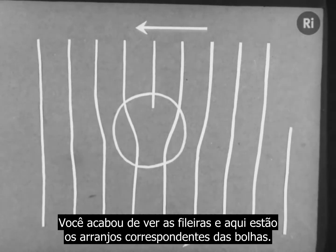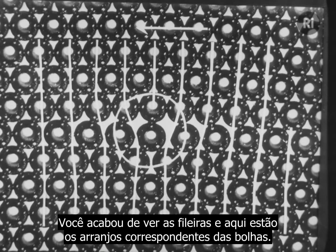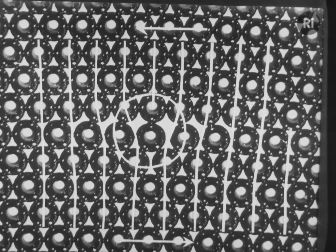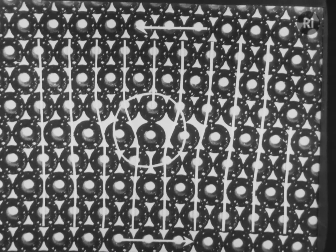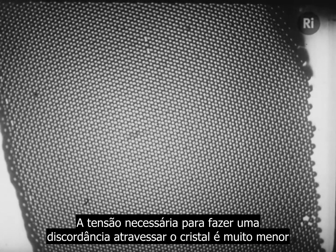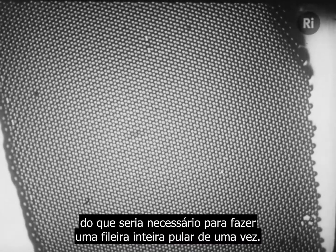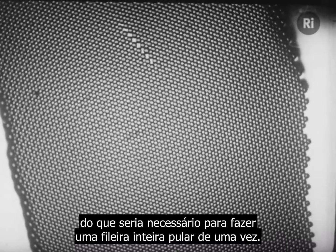You've just seen the rows, and here is the corresponding arrangement of bubbles. The strain required to make a dislocation run across the crystal is far less than that which would be necessary if a whole row jumped at once.